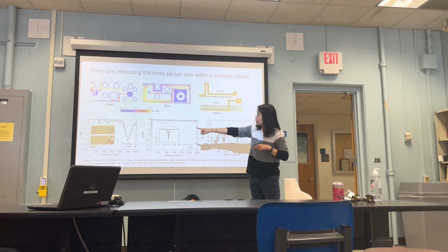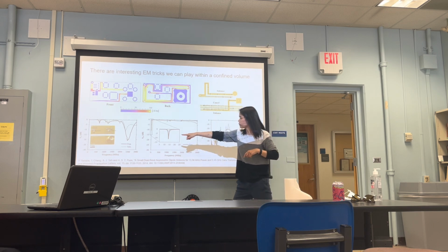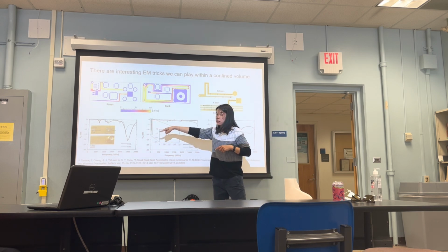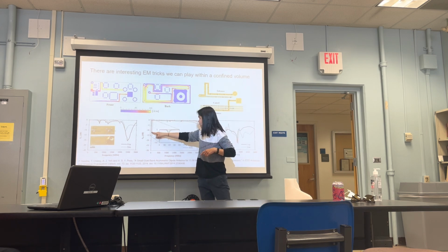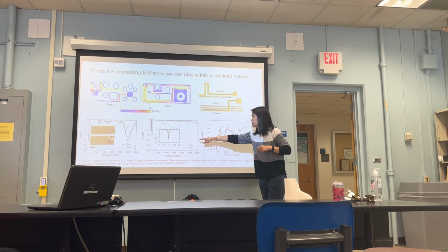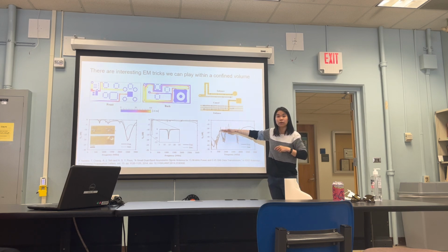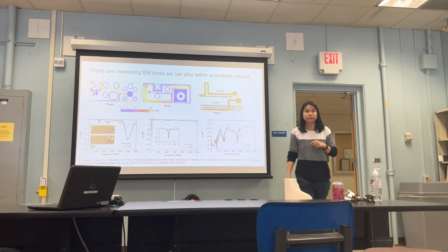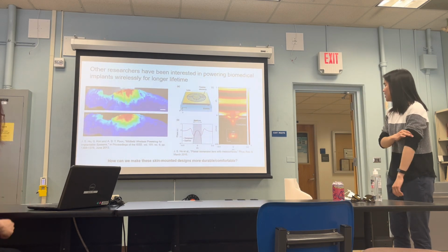And then what we see here on the bottom, the left is the Bluetooth performance, so that's the return loss. This one, all the way at the bottom, much lower frequency, that's the return loss for the NFC antenna. And then this is showing the coupling between the 2. It's fairly low across the whole spectrum. Okay, so that's the first project. We go on to the second one.